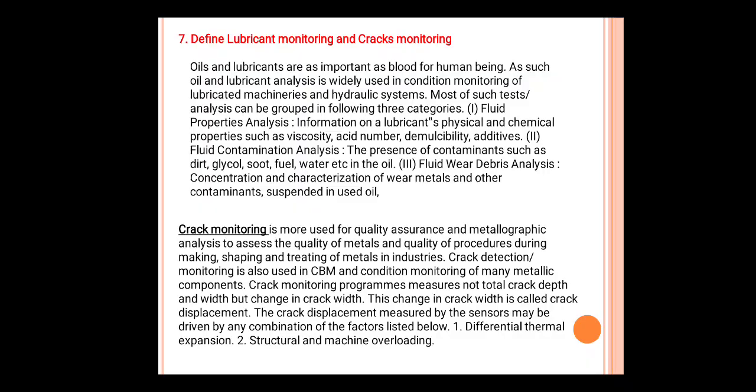Most of such test analyses can be grouped into the following 3 categories: fluid properties analysis, which gives information on lubricant physical and chemical properties such as viscosity, acid number, demulsibility and additives; fluid contamination analysis, which includes the presence of contaminants such as dirt, glycol, soot, fuel, water, etc. in the oil; and fluid wear debris analysis, that includes concentration and characterization of wear metals and other contaminants suspended in used oils.